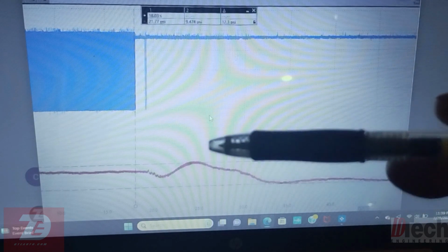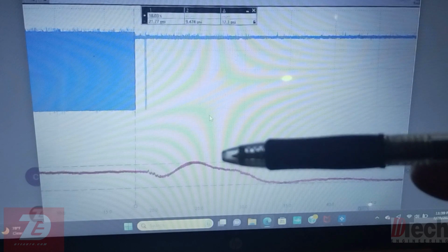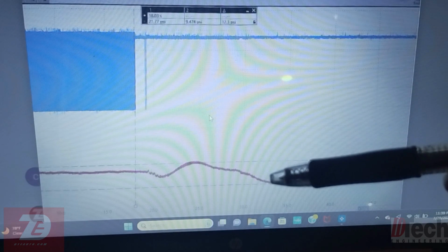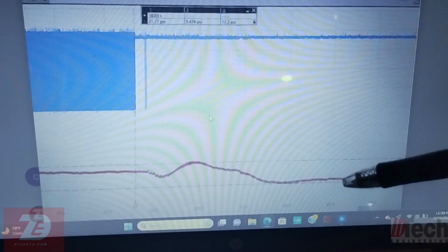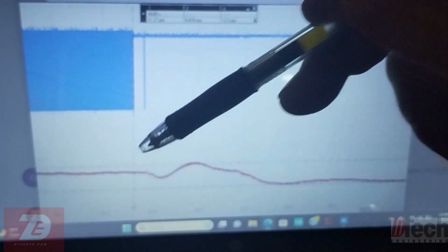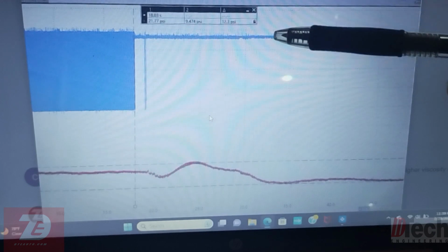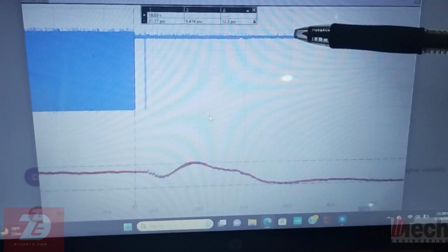But even then, it cannot hold and maintain high oil pressure, and it still ends up dropping off to a way lower point than even the fail-safe point was when the DME started to basically shut off control. But this here tells me DME is not the cause.